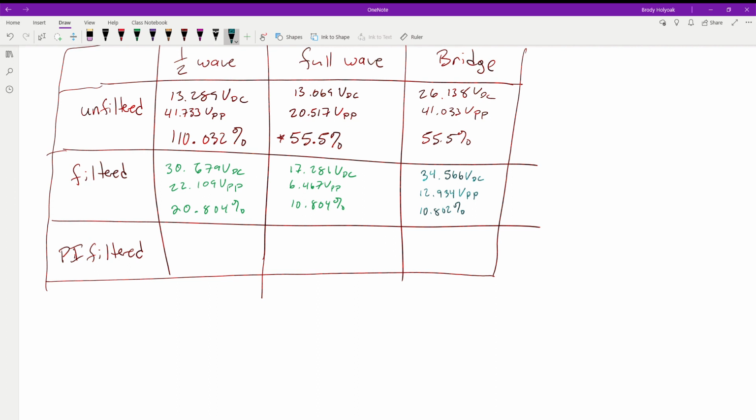With these, obviously we have the 42 volts coming in, so that's kind of our max minus any kind of diode drop as it gets rectified. But the other way we can do that too is we could use a different transformer. So now we can take the 120 volts in, and let's say for some reason we wanted to build a 500 volt DC power supply. Why you would ever need 500 volts DC, I don't know. You're trying to power some big motor, something like that.